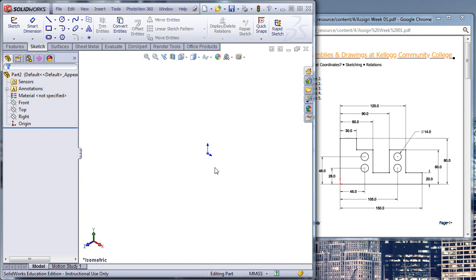Now, you'll notice in our drawing space that we have an origin here. This is real important because everything you do, every part you create, your base sketch has to be connected to the origin somehow. Sometimes that's important where you connect, and sometimes it doesn't really make any difference at all. And then down here is the triad. This is our view triad. Right now, X is in this direction, Y is going up, Z is coming this way. Now, we don't do coordinate entry like we would have possibly done early on in AutoCAD, but this shows you what direction space is.